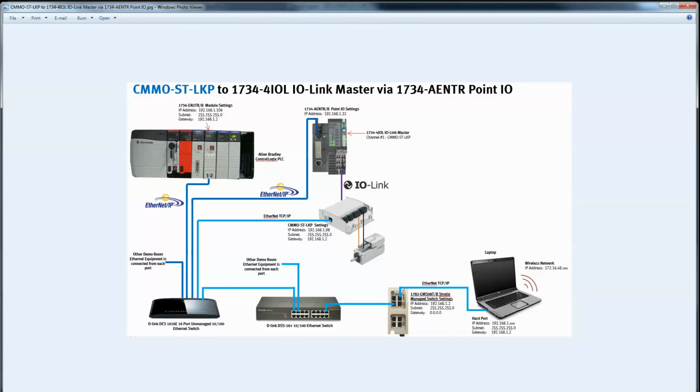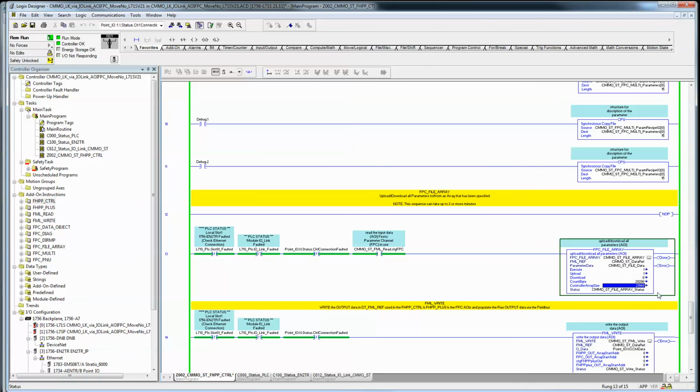What else can I show you here? Well, I guess I'll just let it continue. So it's almost finished here. When it gets up to the 21,948, you should get it done. If you stop this in the middle of its process, likely you'll get a fault, and you'll need to cycle the controller again, because it changes some things in the controller. So you have a done bit, you know it's finished.